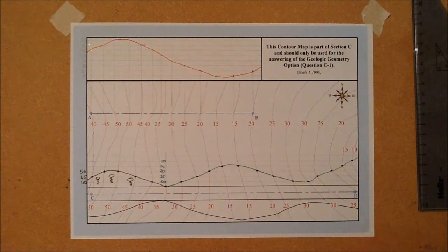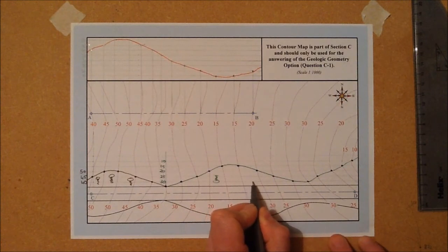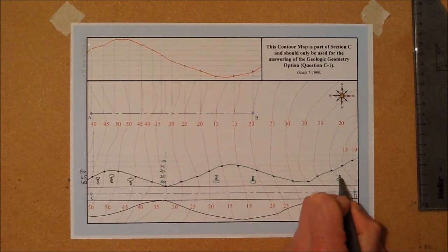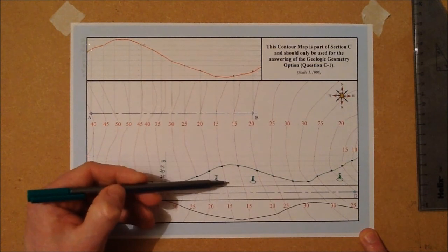One last thing to do with that drawing, we need to show which way the tadpoles would be climbing, which is a way of identifying which way the slope is going in relation to the road. If the tadpoles are facing towards the road, it shows us that they are swimming uphill, so we know the hill is coming from this point out, coming up towards the road.